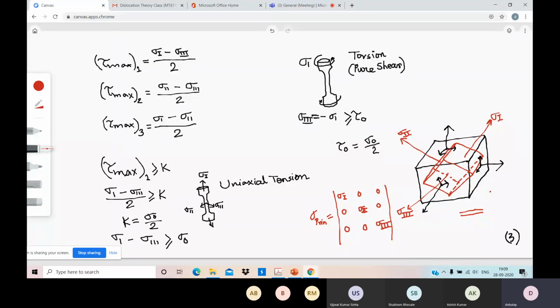components on the body. And inside this parallelepiped, you can draw another inclined parallelepiped where the face planes are basically three sets of principal planes, where the red parallelepiped is your principal planes with principal stresses sigma 1, sigma 2, sigma 3. And on those face planes there is no shear stress, because you know a principal plane contains only normal stress with no shear stress.